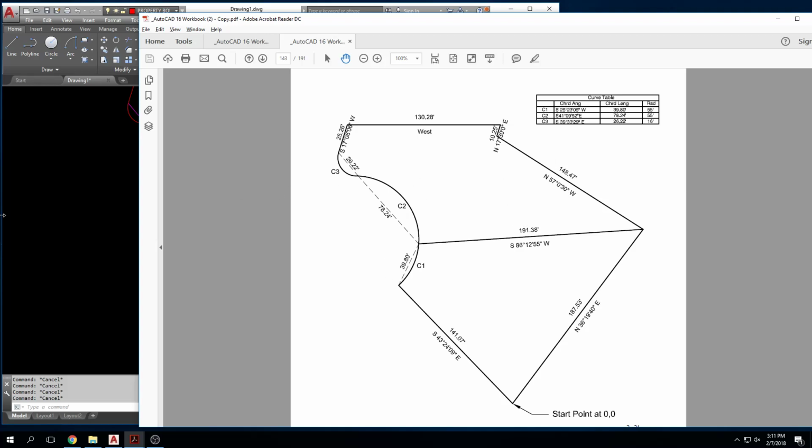Okay, so now I look at it. On that intersection right there, when you want to snap your arc, do you want it to snap to the chord line or the actual intersection? You want it to go to the end point of the chord, because the chords are what are defining it.